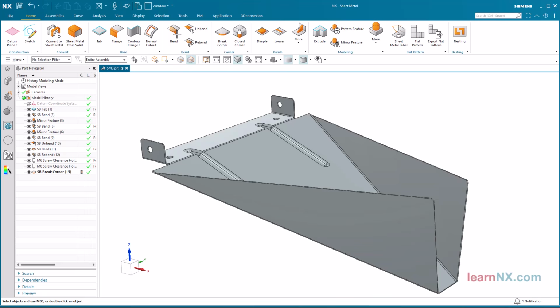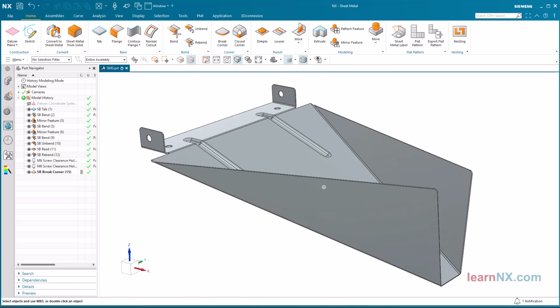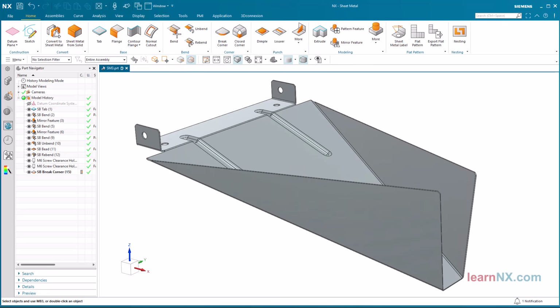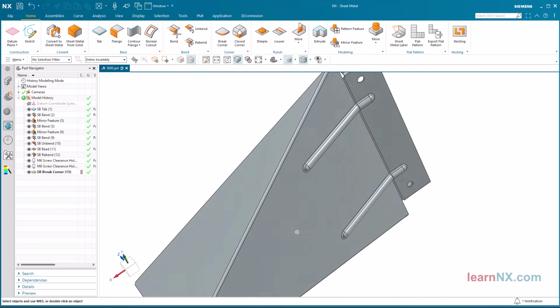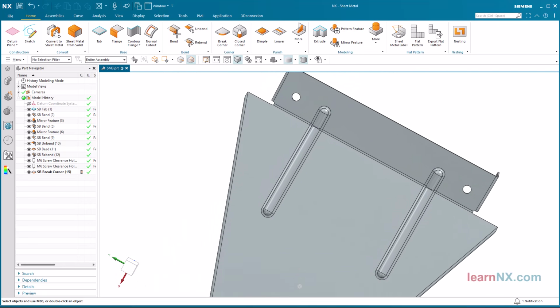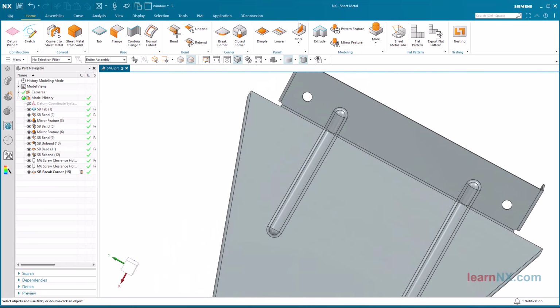And so, in just a few steps, a rectangular plate becomes a part chute. The inserted beads run across the bend. The unbend and rebend commands can help here. Turning a bead upside down can sometimes cause problems, but the issue is easily identified.